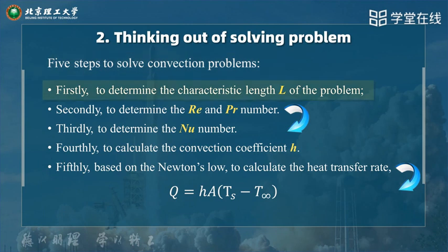Firstly, we should determine the characteristic length L of the problem. Secondly, we should determine the Reynolds number and Prandtl number.